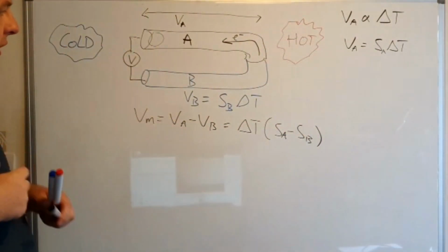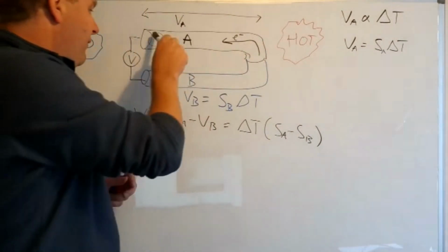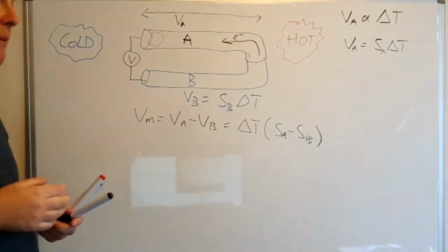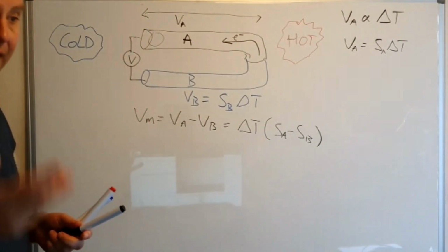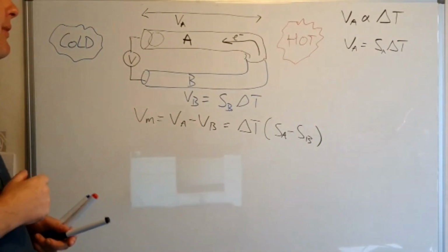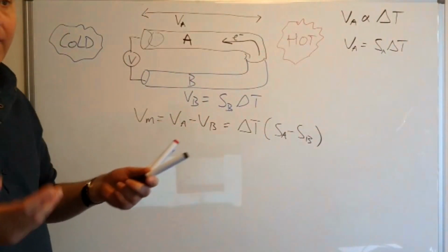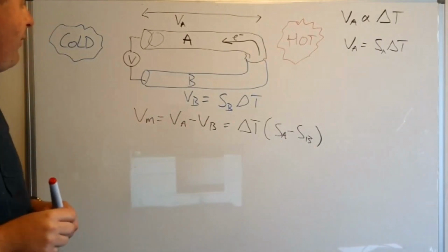And so with a thermocouple, what you do is you choose a different type of thermocouple, which is giving you different material combinations, which are then sensitive to different temperature regimes. And so you pick one type of thermocouple if you're trying to operate up to, say, 1000 degrees C. That's typically what's called a type K thermocouple. And you have a different type of thermocouple if you're going up to over 2000 degrees centigrade. Typically you might use a type C thermocouple there.